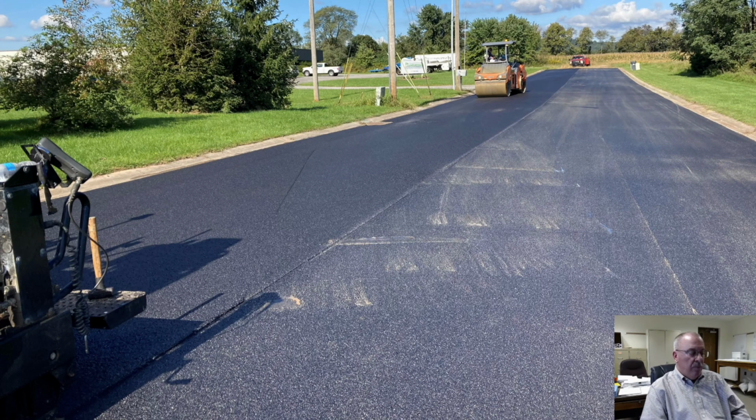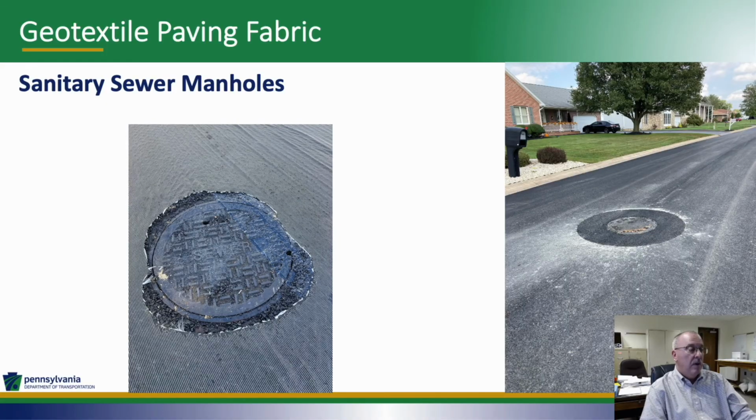This is a view of the completed wearing course over top of the fabric. The contractor was doing the compaction. We had several sanitary sewer manholes on this project. In the photo on the left, you'll see how the contractor cut the reinforcing paving fabric around the manhole cover prior to the overlay. After the paving contractor was complete, the township went in the following week and cut the new road to raise and install new watertight manhole covers.